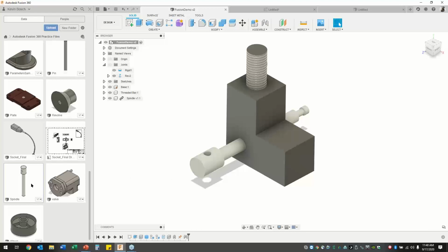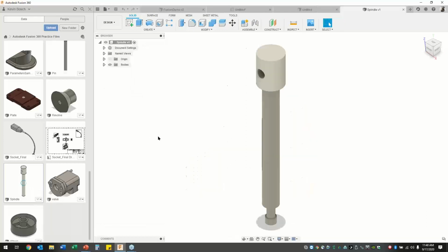If we go in and open this particular part, it has its own setup. Now, I actually brought this particular part in from Inventor, so we're not seeing that timeline view. But if you create it here in Fusion, you would see that timeline view. If not, then it's still native to Inventor. You can still make those changes, bring those back into the project if it's not part of the project already, and see the different updates.